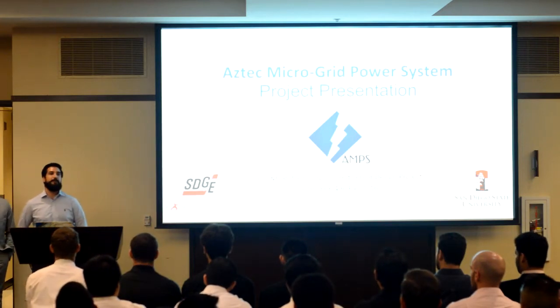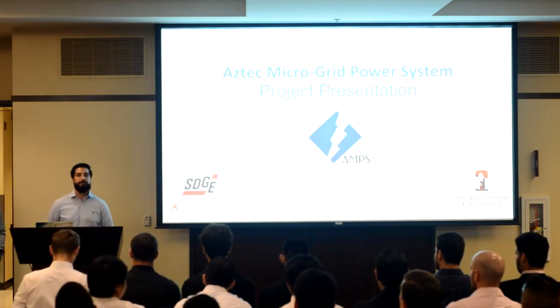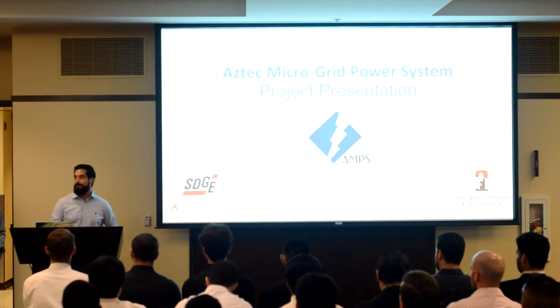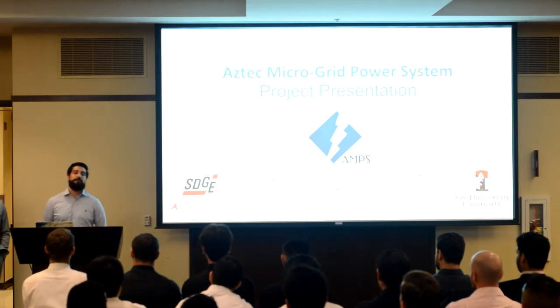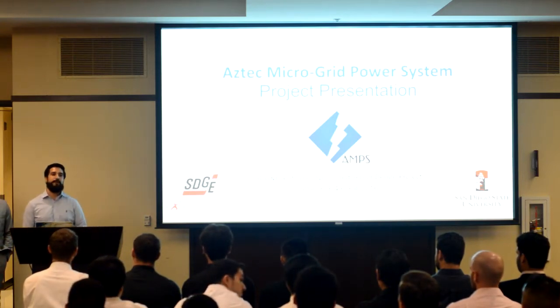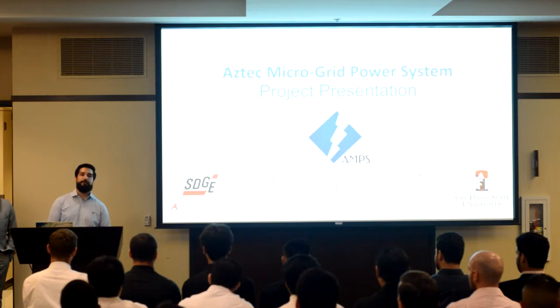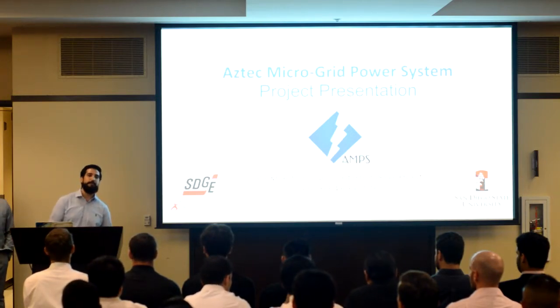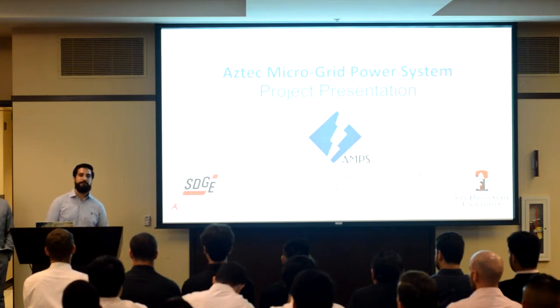Now, there are many people nowadays switching over to renewable energy sources, such as solar. But what they don't know is that there are many inverters out there that don't produce an adequate sinusoidal waveform. So, to give you an example, if you use a modified sine wave inverter, and you plug in your cell phone charger or turn on your LED lamp, you will increase the total harmonic distortion.